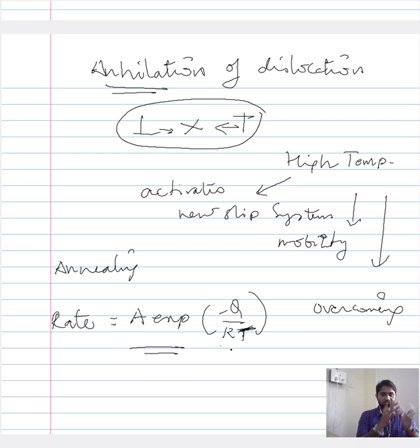With an increase in the dislocation density, the system's energy increases. So in the general case, we do annealing to reduce its energy, but in the case of creep behavior, we already have a temperature above room temperature that allows whatever mechanisms happen in creep to occur in the current system.